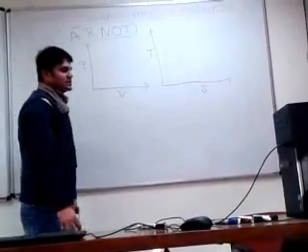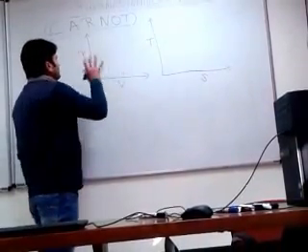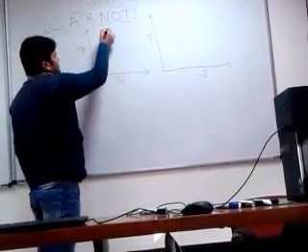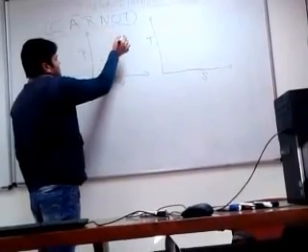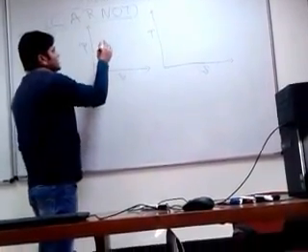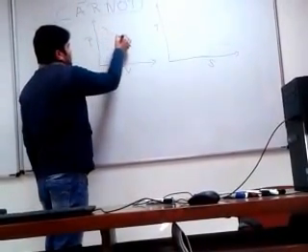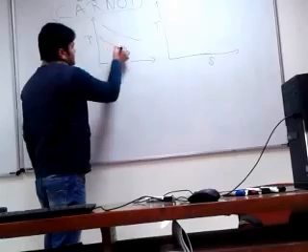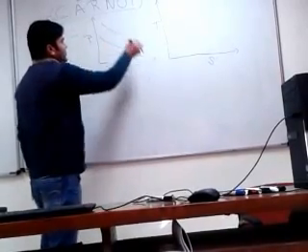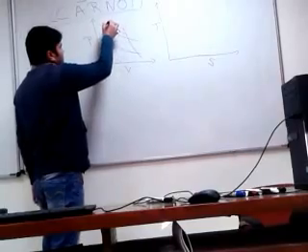As we know, the Carnot cycle has two adiabatic processes, and the slope of adiabatic on the PV diagram is negative. First we will draw the isothermal. The slope of the isothermal process is less than the adiabatic process, so there are two isothermal processes, and the slope of adiabatic is more than the isothermal.